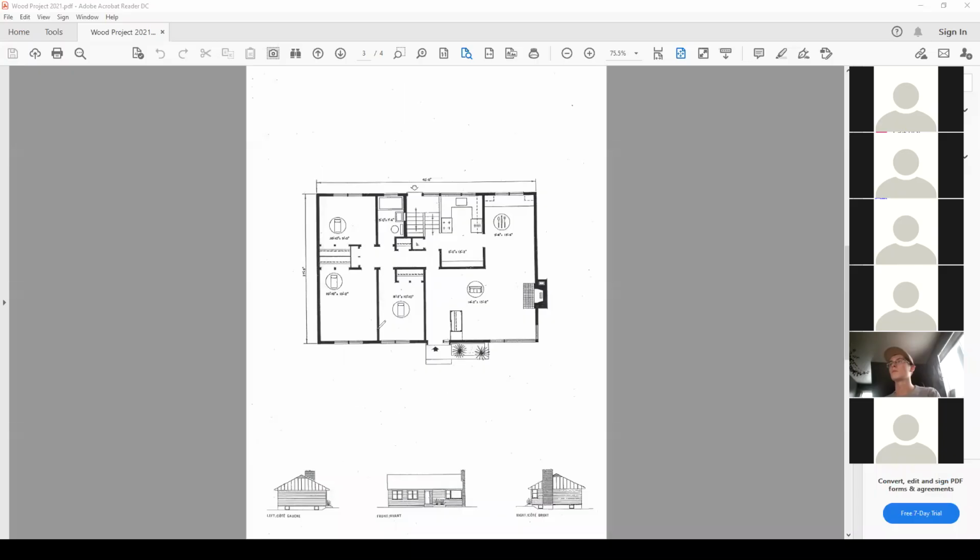So in this case, normally the way it's done is that you would have to design the floor, where you have to decide where the floor is, and therefore the floor gets designed. Then normally in this type of house, the roof trusses will literally span and be supported only by the outside walls here, like this. So therefore these are all non-loading partitions. They will not be supporting the roof at all. The roof truss will be supported from here to here. So that's how we're going to be designing the roof truss.